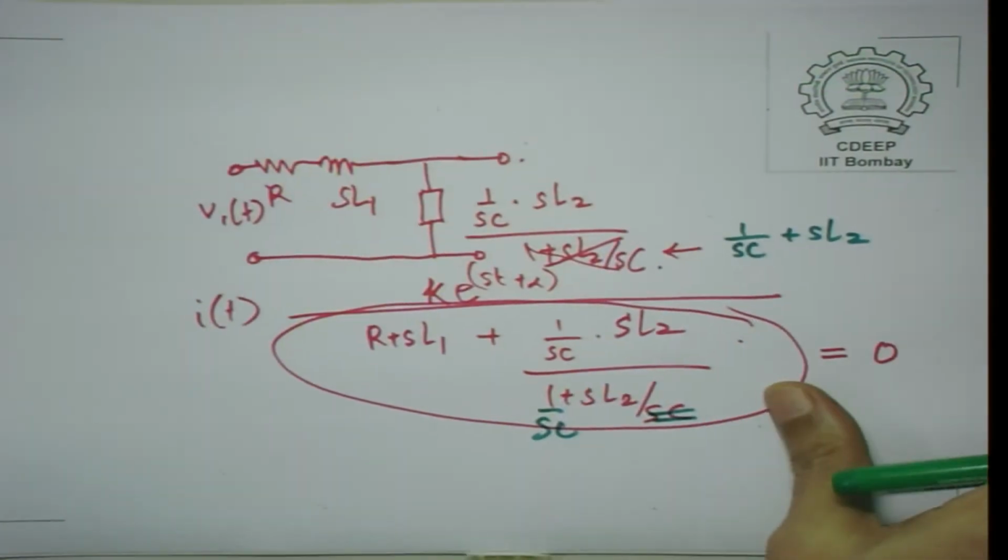Okay. So, to summarize, you have a natural response and a steady state response in linear circuits. The steady state response has the same wave shape as the input waveform. If it is of the form e raised to st, we can represent sinusoids also as e raised to st, because you can plug in S is equal to j omega. Remember that linear circuits also satisfy an important property called superposition, in the sense that if you have an input with 2 frequencies, you can get the steady state response for this composite input by getting the steady state response for each of them separately.